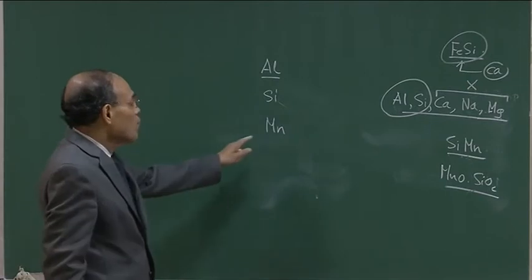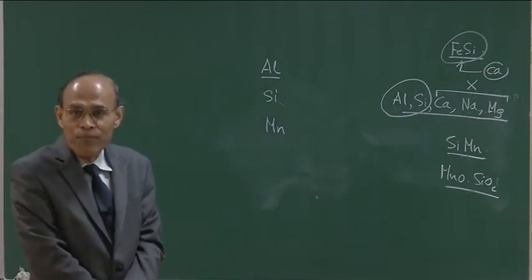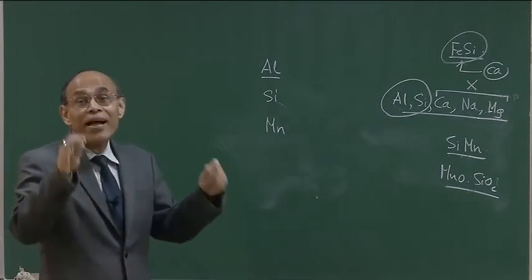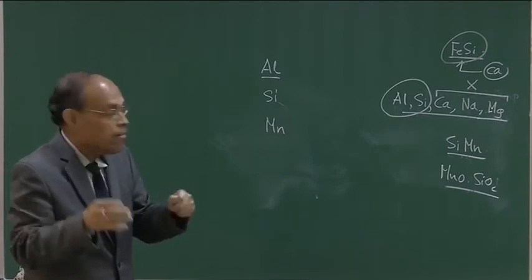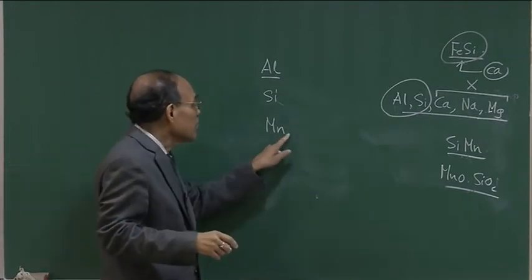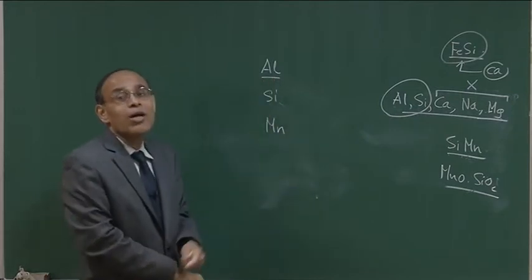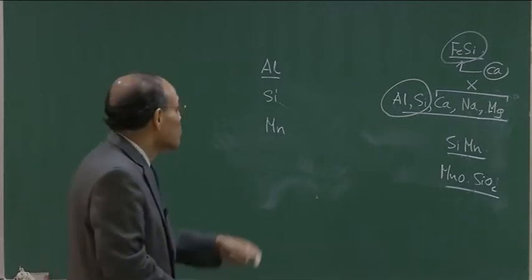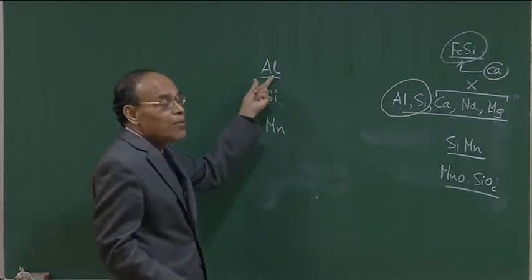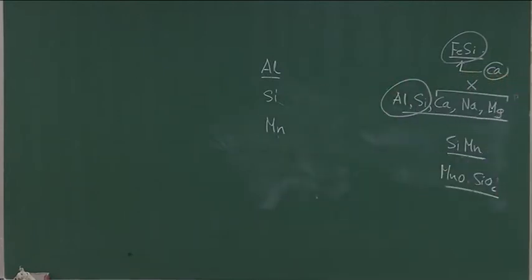If you want to get 10 ppm oxygen with manganese, the manganese concentration in steel could be about 10 wt%. On the other hand, if you get 10 ppm oxygen with aluminum, the aluminum content in steel could be only about 400 ppm, and this is because of the simple fact that aluminum is a far more powerful deoxidizer, and this follows from the equations that I have written here.